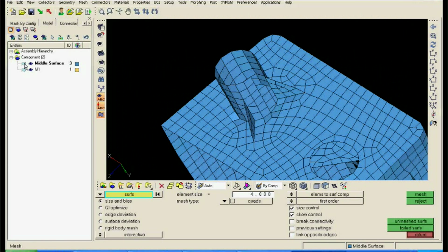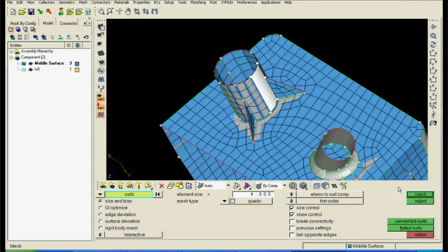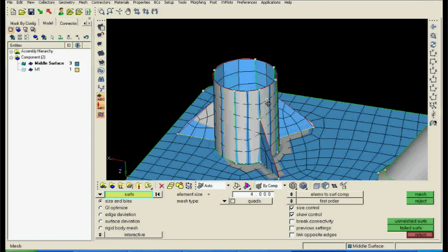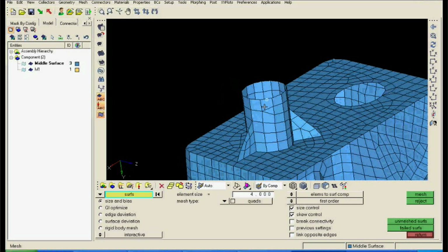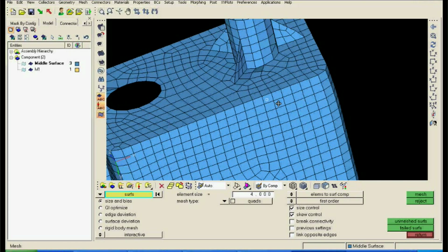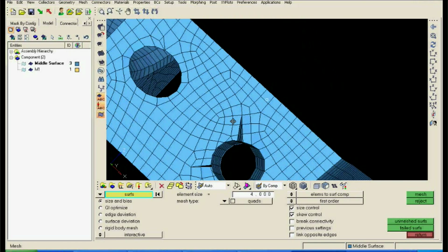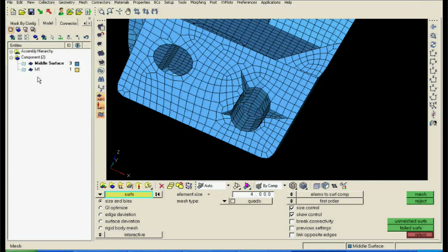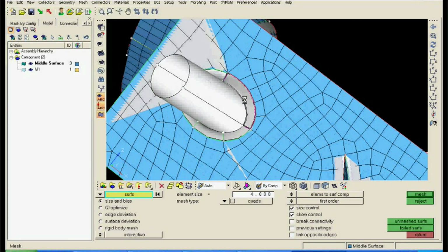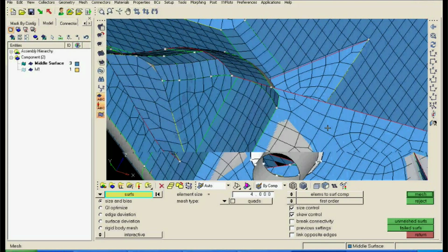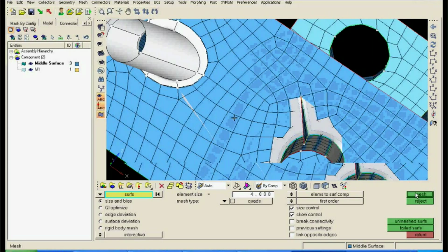So again, the use of creating this cut is, you can see that we have a nice mesh pattern here as well. I could have thought of removing this tria, with the element size increasing or decreasing. That could have also worked out. That's not an issue. So in this way one can think of dealing with such a problem. And again on this side I need to mesh all these surfaces. And I make sure that we have the same number of nodes for better element quality.